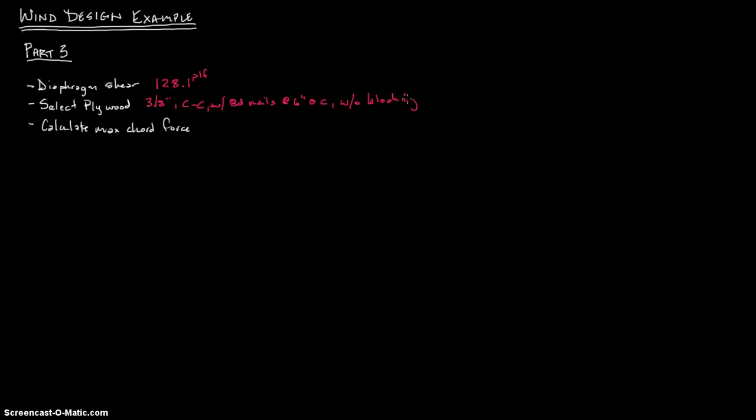It says this diaphragm has an allowable shear of 160 pounds per foot, so I'll go ahead and write that. 160 PLF, and we'll say it's capacity. So that's greater than the 128, so we're good. Now we will need to calculate the max chord force.